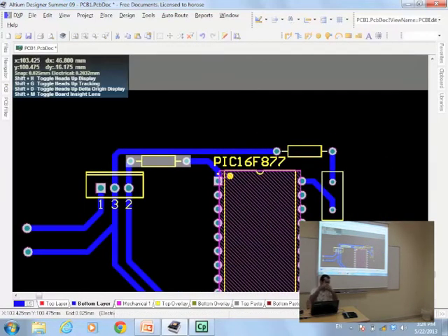There's an LED and a resistor in the path. Yeah. There's another pin for VDD and VSS on the other side. You don't need to connect them. They are internally connected together. Sometimes if you want to use more pins that send signals to lots of switching things, you need more power on those pins. You connect all of them. Or sometimes just for flexibility. Sometimes you put it on the board and it's very hard to connect the things from here, so you go from the other side.